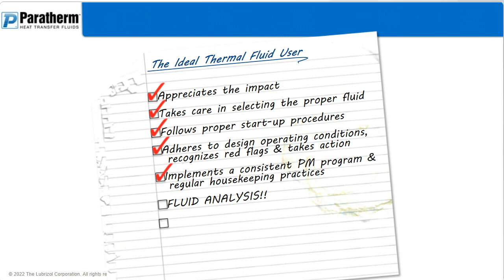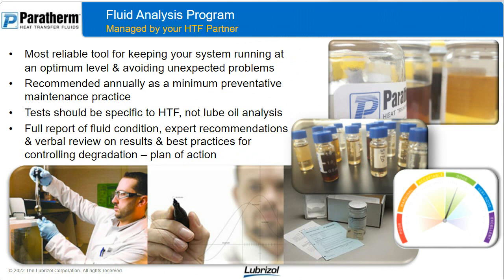To me, this next aspect is extremely important, and that's fluid analysis. You should be getting a fluid analysis done minimum annually. A fluid analysis is the most reliable tool for keeping your system running at an optimum level and avoiding unexpected problems. You should be getting this as a preventative maintenance practice annually, but also after any major changes.